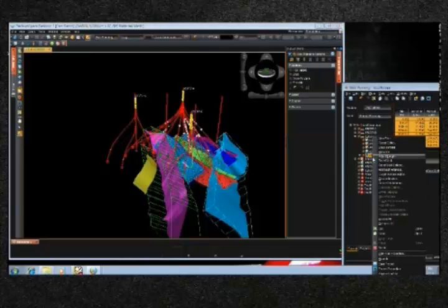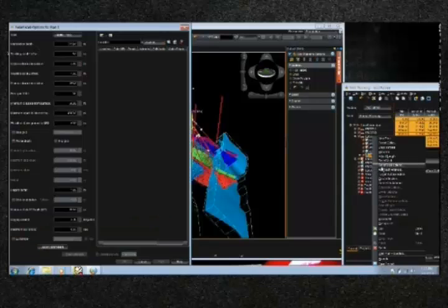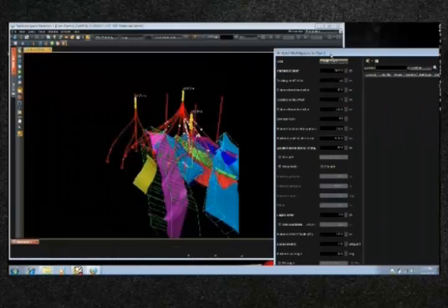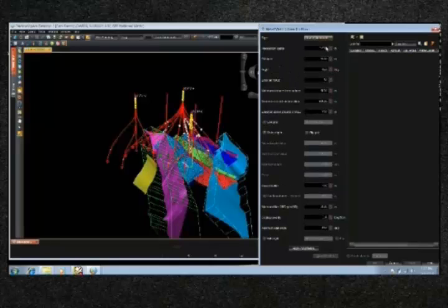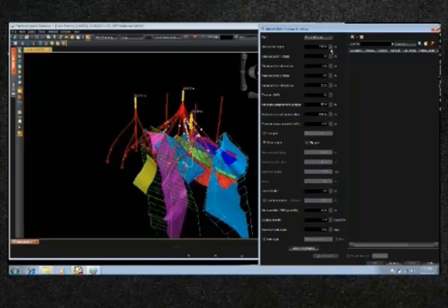To then come up with the relief well plan options, we simply bring up the dialog as required, and from within this relief well plan options dialog, we can start to specify the type of relief well plan we would like to create. There are three options available to us, including the simple oriented intercepts as well as the parallel track method. We use the parallel track method in this particular demonstration,